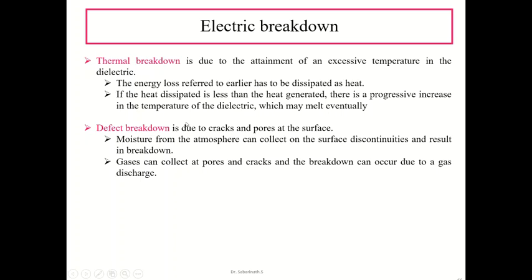The defect breakdown is due to cracks and pores at the surface. Another breakdown is a defect breakdown, where moisture from the atmosphere can collect on the surface discontinuities and result in breakdown, and gases can collect at pores and cracks, and the breakdown can occur due to a gas discharge. So these are the two breakdowns, thermal breakdown and defect breakdown.